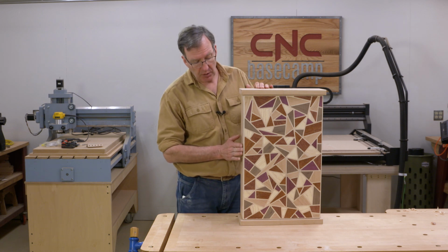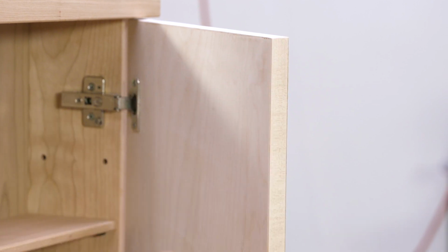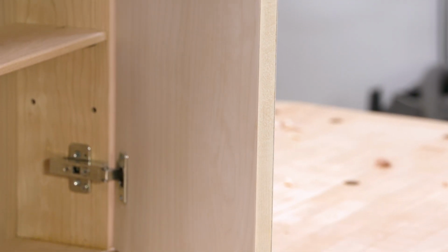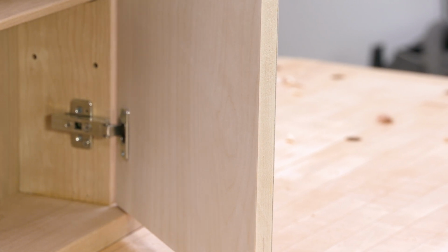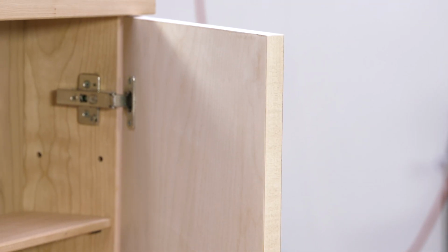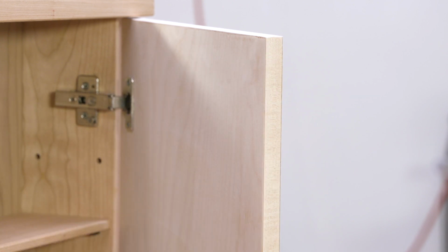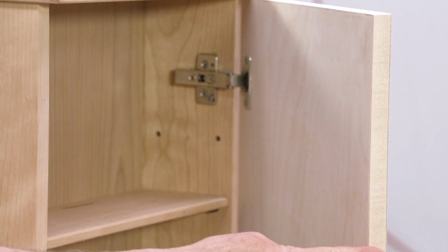Well, I've got my cabinet all assembled, so let me point out a couple of details. First, let's take a look at the door. One thing I've done is to add some edging around the exterior after I got it cut and fit to the correct size. Now, I've never liked wrapping wood all the way around the outside of a door where you can see the glue line on the face. So instead, I just created a rabbet and I went up to about the second layer of veneer on this plywood, cut some 1/16 inch maple and glued it in place. Makes for a nice clean look on the front, nice clean look on the edge.